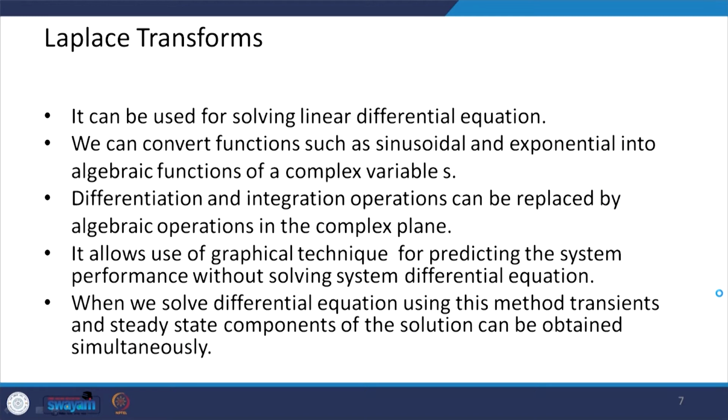So, what is basically the Laplace transform? These Laplace transforms are used to convert differential equations into algebraic equations. We can convert functions such as sinusoidal and exponential into algebraic functions of a complex variable s. The differentiation and integration operations can be replaced by algebraic operations in the complex domain. It allows the use of graphical techniques for predicting the system performance without solving the differential equation. That is one of the very good advantages of the Laplace transform.